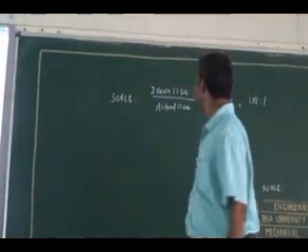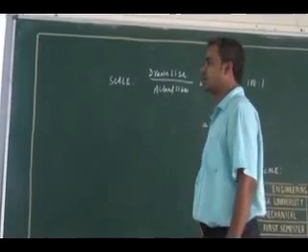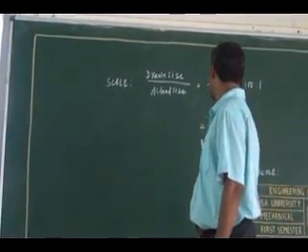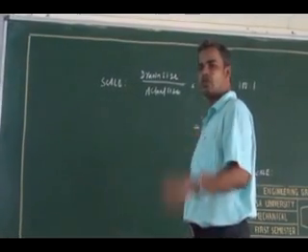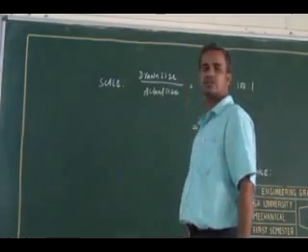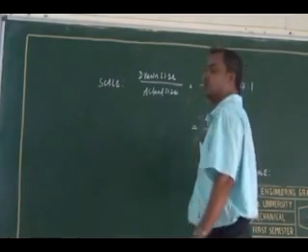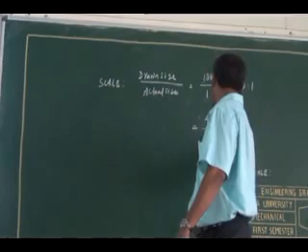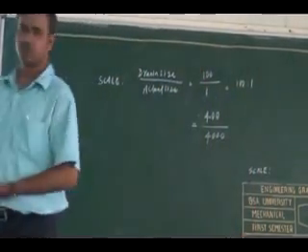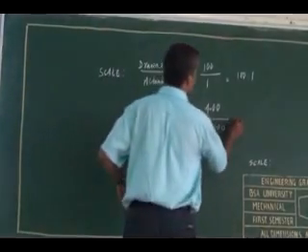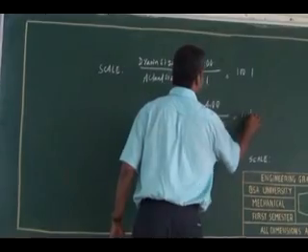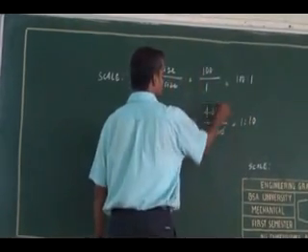So the actual size we are going to draw is 4,000 mm, and we can reduce it to draw it as 400 mm. So I am going to draw the length of the machine as 400 mm, while the actual length is 4,000 mm. The ratio will be 1:10, as two zeros get cancelled.